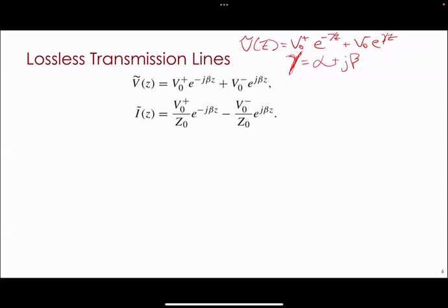As soon as you see an e, that's the exponential. The j means that's a complex exponential. With a complex exponential, you can use Euler's formula and turn it into cosines and sines. When we go back to the time domain, we only take the real part. So we're only taking the cos part. And that's the relationship between all that stuff we did before with the time domain waves.